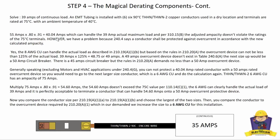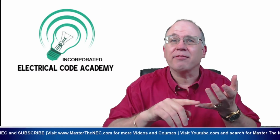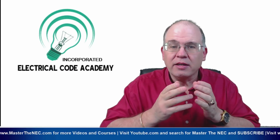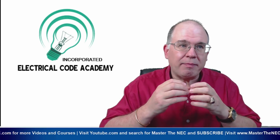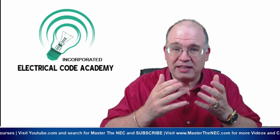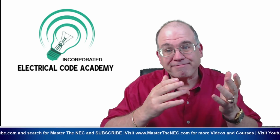No. However, at this point, you're an electrician and you're thinking, I sized it for the adjustment. I sized it for the correction. I'm good. It's an 8. Now I have to protect that conductor at its ampacity. The ampacity of that conductor now is good at 40 amperes, 40.04. That's what its ampacity is. So at this point, I got a problem.